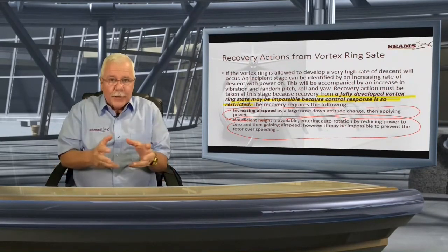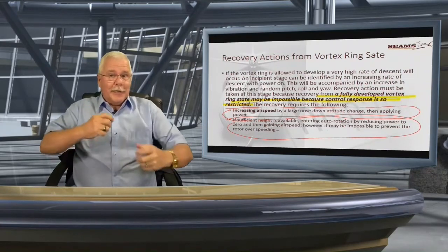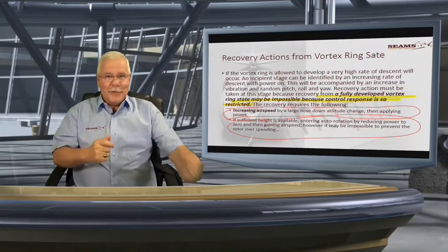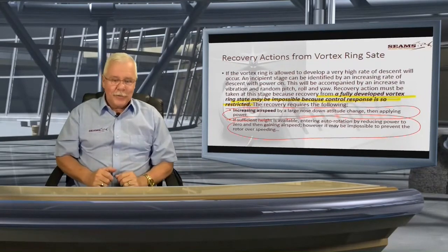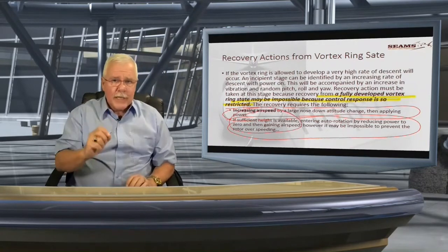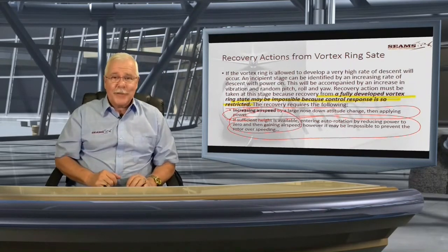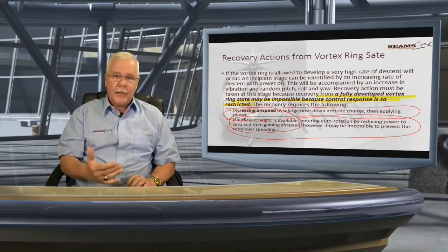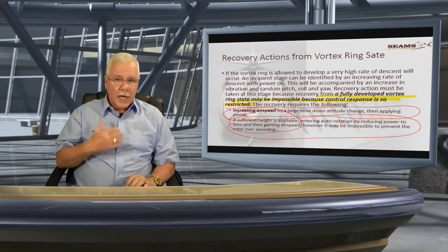This is not a thing that you can say, okay, here I'm sitting at 100 or 120 feet, I think I'm going to autorotate. There's no way. The moment you lower the collective, you get yourself into the ground. So this is only when there is sufficient height. And you really, really, really got to make sure that that is the condition. Well, I know where I'm working. I know that I'm working at low level and I can't work with this. I really do know that.